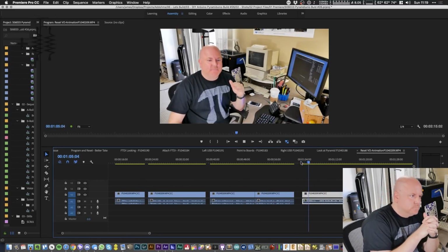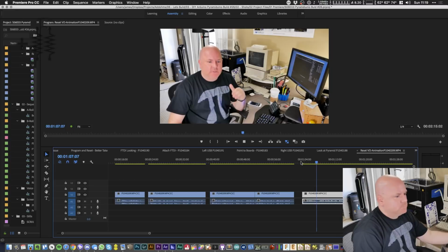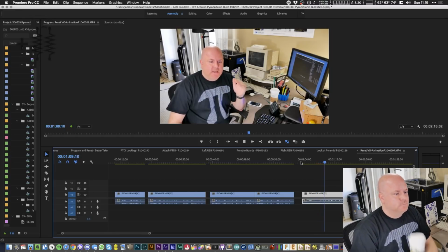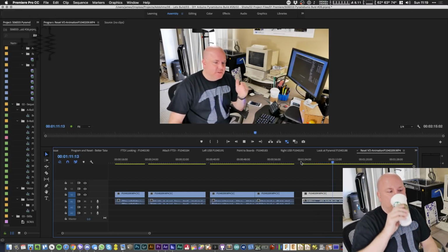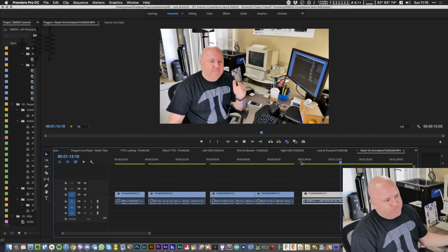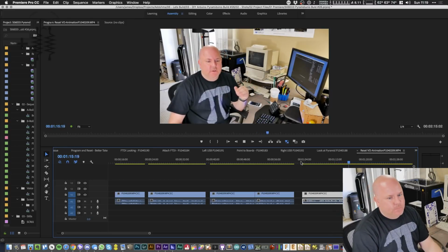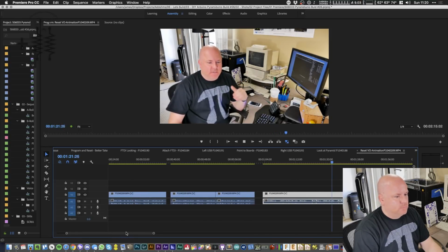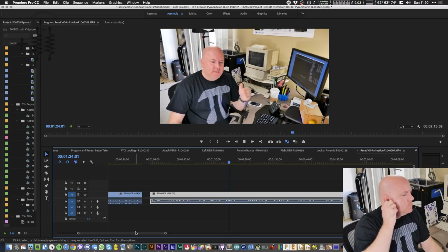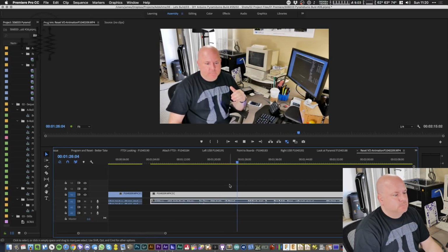These two signals are connected by a 100 nanofarad capacitor. When the serial port is closed, that means the capacitor sees 5 volts on the DTR side and 5 volts on the reset side. So when the computer opens the serial port, the USB to serial chip asserts the DTR signal, which causes one side of the capacitor to go low.